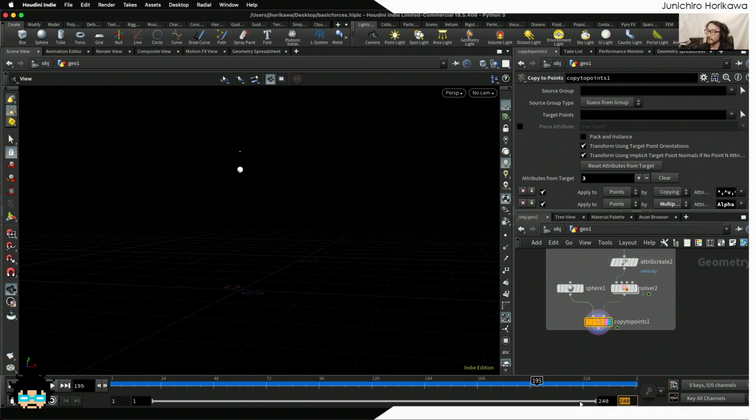Let's increase the number of frames. And you can see that slowly it's changing. It's slowing down, going downward, downward, and downward. But you might have noticed that it's in the air way too long. Consider if it's a real-world environment. The bouncing continues for a really long time. That is because we haven't set any friction for the bouncing on the floor. So we could try to implement this friction with a simple equation and make the ball go much slower than the current pace. So let's try to do that.